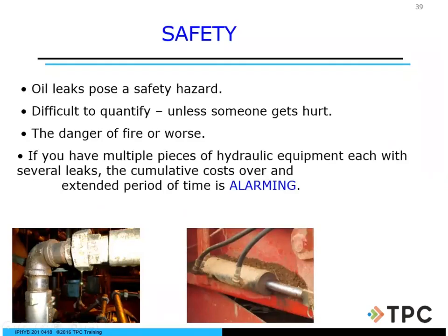So oil leaks pose a safety hazard, 100%. If we have some oil leaking on the floor, somebody walking by is going to slip and fall. So that's another issue. We need to make sure that hydraulic fluid does not leak on the floor or anywhere else, because it does cost money. And then the efficiency of our system has greatly decreased. We have a huge hydraulic system. We want to be as efficient as possible. We want to push this load or pull this load, whatever we're doing. We want to make sure we do it in a professional manner where the hydraulic fluid does not leak.